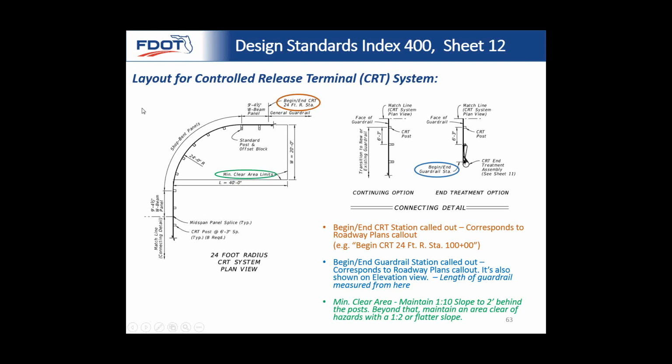These are all breakaway posts. The only reason this guardrail functions with a 90-degree impact is that all of these posts break away to absorb energy, and then you have a really large deflection back here that takes up almost the whole clear area. All that deflection is absorbing energy, keeping the vehicle from passing through, and capturing the vehicle.